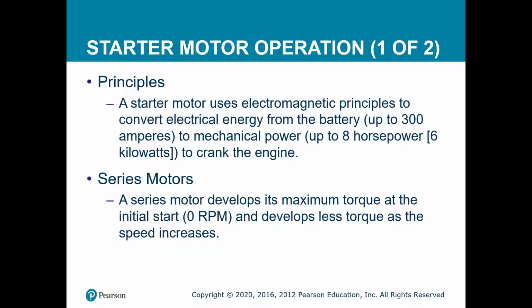Just understand that as a starter takes power, it makes power at the same time, and those two forces, those two magnetic fields, will actually push against each other and fight each other. So that's why we use a series motor. Typically in a starter, it'll start out nice and fast, but then as it starts to generate its own power, it will actually slow down.